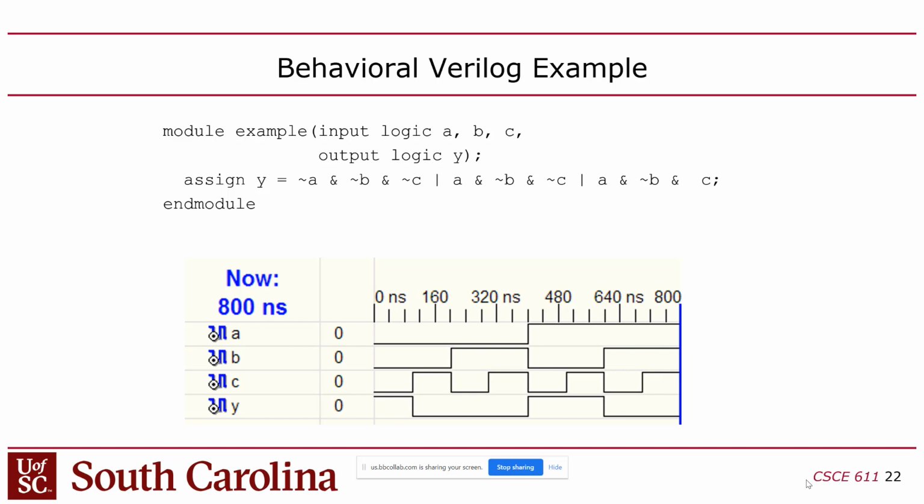Normally you can't do that, especially if these are sequential circuits where time is also kind of an input as well. So usually you have to pick and choose how you stimulate the inputs to expose different test cases, which test vectors are called. But basically the point here is that we're going through all the A, B, and C's, and then we're looking at the corresponding Y. So you could literally just translate this into an 8-row truth table if you wanted to.